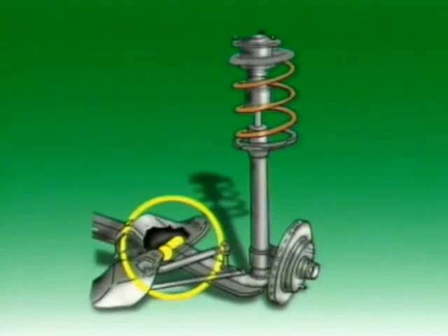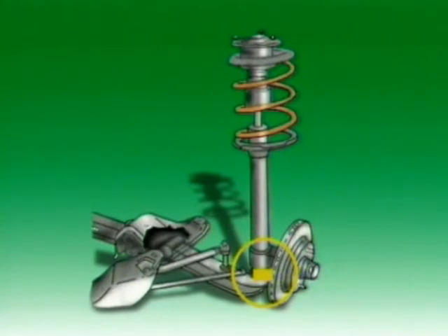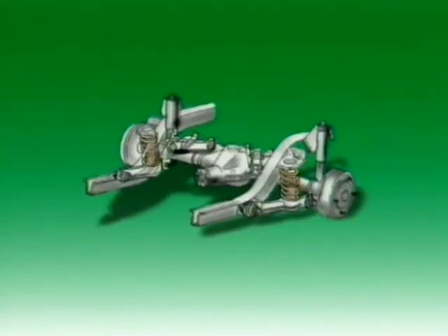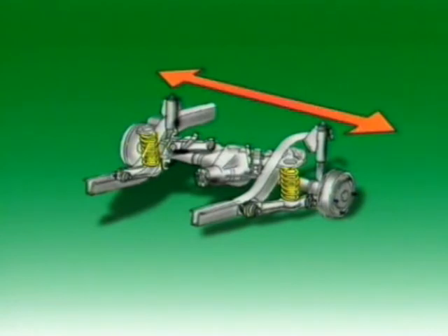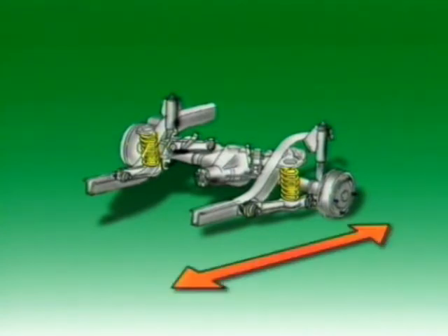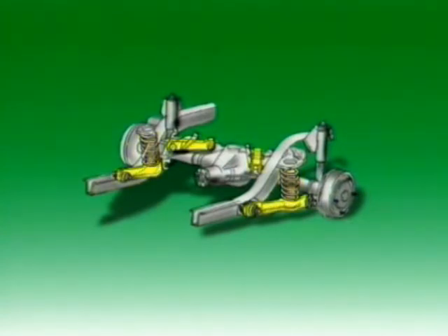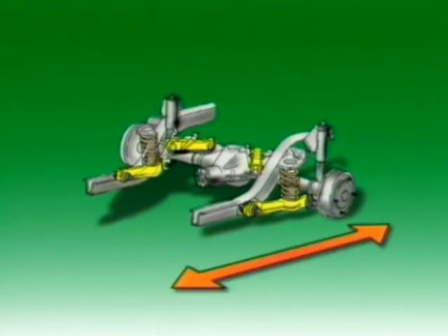The inner end of the control arm is bushed to the vehicle body, and the outer end uses a ball joint to allow changes in the steering angle for turning. This rear-wheel drive vehicle has coil springs in the rear suspension, therefore special provision must be made to locate the axle, laterally and longitudinally. Trailing arms or control rods are used to position the axle longitudinally.